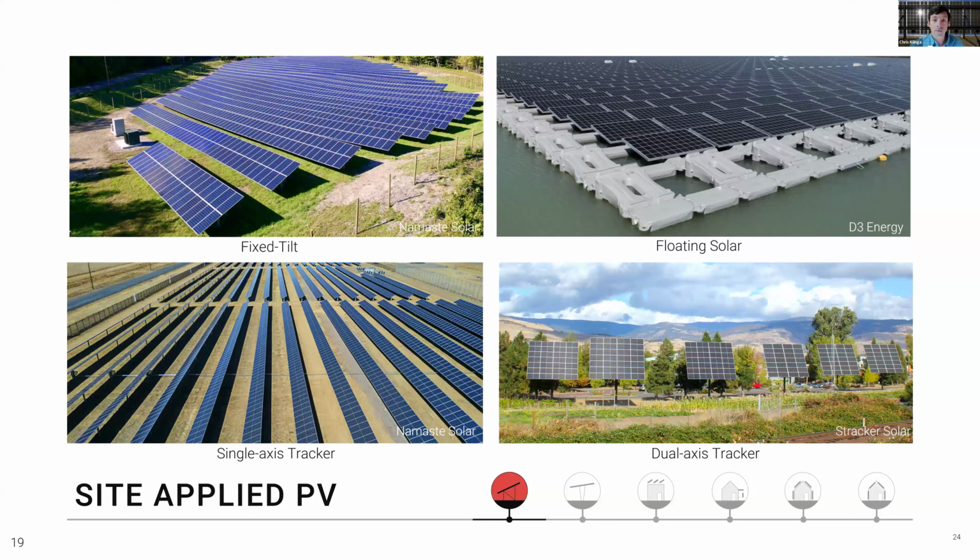The benefit of fixed tilt arrays being that they generally require less land, but yield less energy on a per kilowatt basis when compared to the trackers. Floating solar is great because it does utilize space that is otherwise underutilized in some instances.